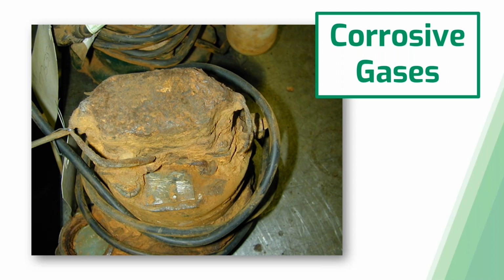That water level will always go below the top of the pump. Whereas having a non-automatic pump with your float switches placed above that pump is going to keep that water level above that pump at all times, thus protecting your pump from those corrosive gases.